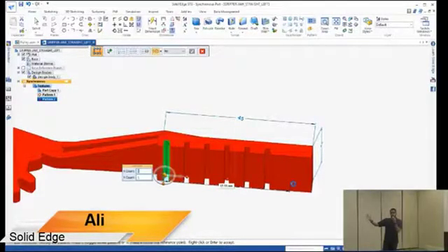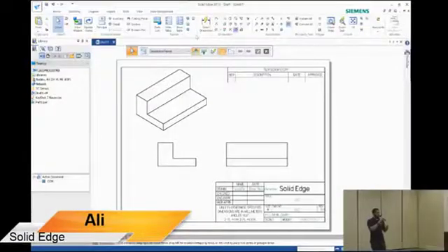Now, in the next video that I have, I'm going to show you guys how you can make your mechanical drawings with our program. You don't have to sketch it on a piece of paper anymore, dimension and all that stuff. It's very old. In our program, you can basically bring in any part that you made and make engineering drawings that you guys can see. It's going to automatically recognize the views that I want. I'm going to bring in three different views from different sides of this simple part that I made. And what I'm going to do is use the smart dimension and dimension it.